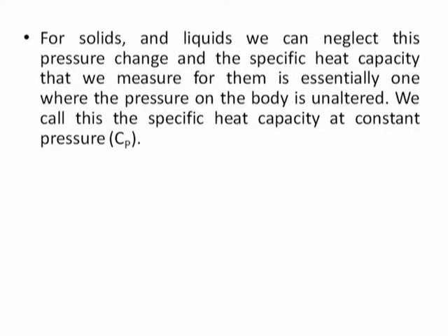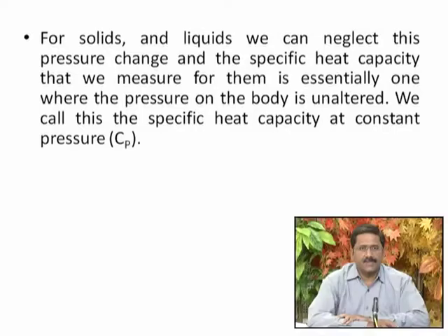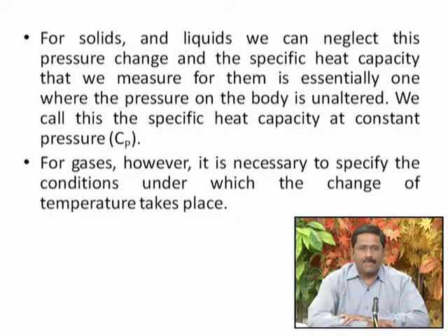For solids and liquids, we can neglect the pressure change, and the specific heat capacity that we measure for them is essentially one where the pressure on the body is unaltered. We call this specific heat capacity at constant pressure, Cp. For gases, however, it is necessary to specify the conditions under which the change of temperature takes place.